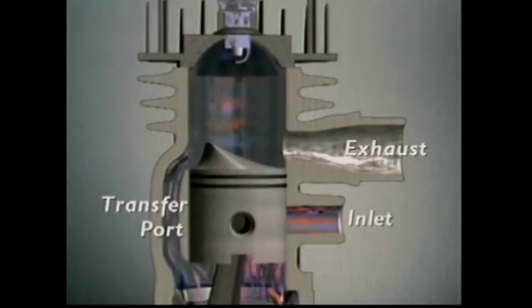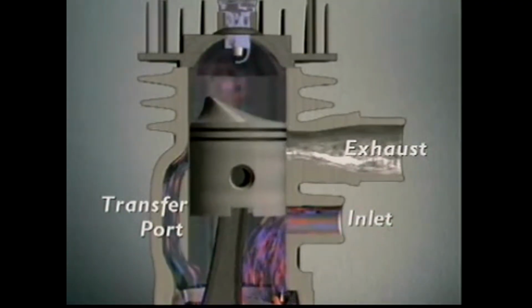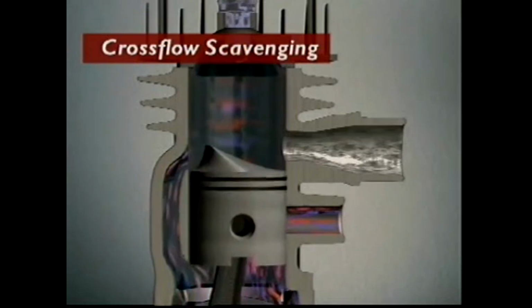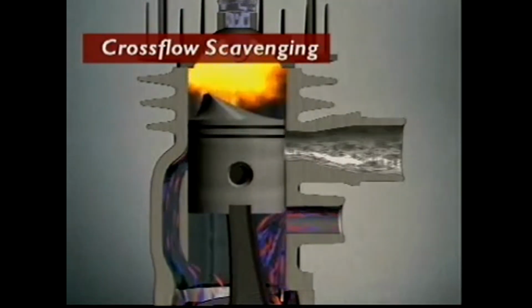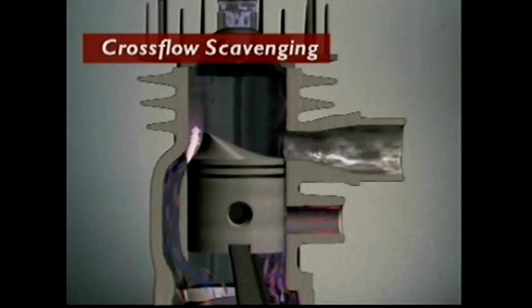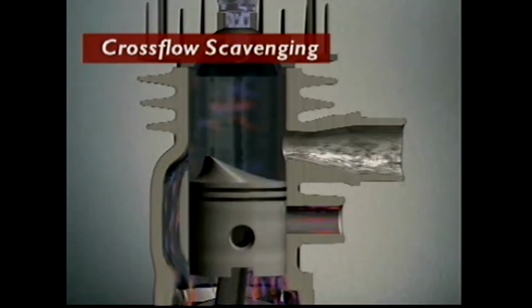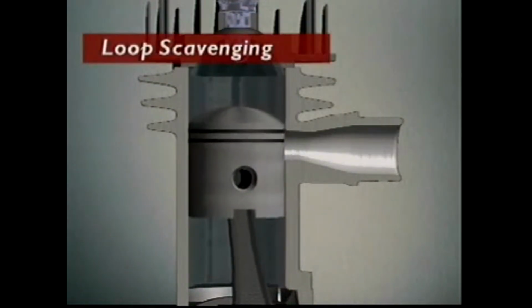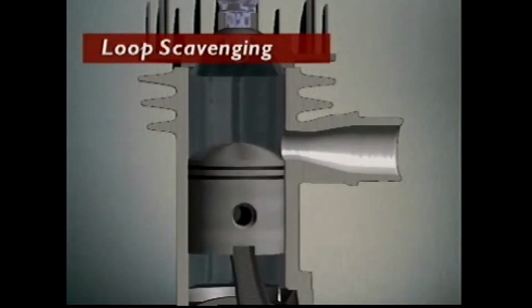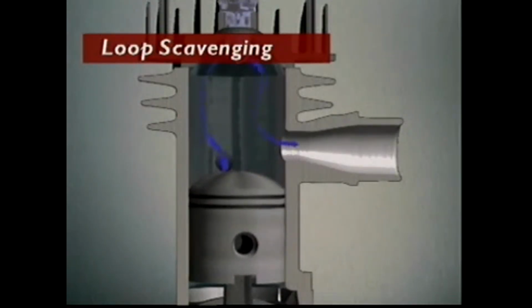How scavenging occurs depends on the design of the cylinder and ports. Cross-flow scavenging occurs when mixture enters on one side of the cylinder and exhaust gases escape on the other side. No valves are used and mixture flows across the cylinder. Loop scavenging means mixture enters the cylinder across the top of the piston and is caused to flow upwards in a loop before moving in the direction of the exhaust port.